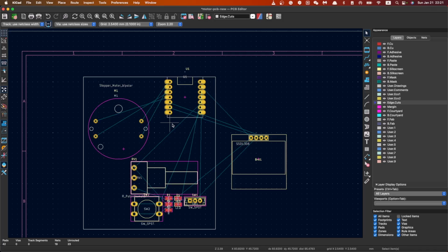And to make sure those through-hole pins and SMD surface mount pins can be connected on one side of the PCB board, the first thing you're gonna do is to flip all the through-hole pin devices to the other side of the board. The way of doing this is pretty simple: select this item first, then press F for flip.